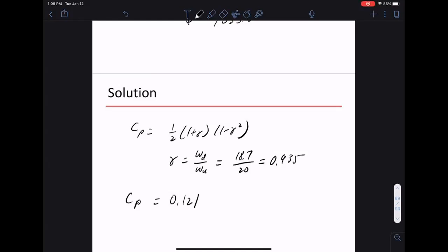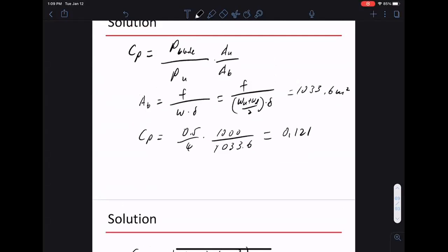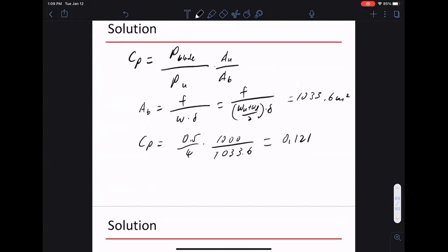Okay, so this is a quite common example. The main thing to remember is often people forget about this area correction term. Sometimes you tend to see the total power upwind and the power extracted by the blade, and you just divide them and say that's the efficiency you have. That's not exactly correct.